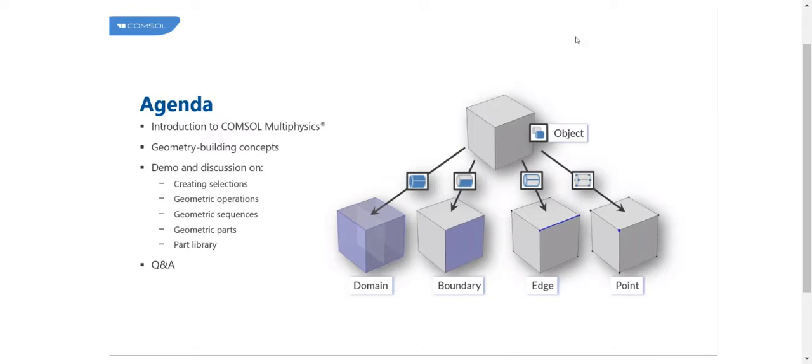We will also discuss how to use the geometric sequence, geometric part, and part library. We will walk through various geometric operations that are specific to the CAD Import Module and Design Module, such as defeaturing, repair, thickness, and all additional features.